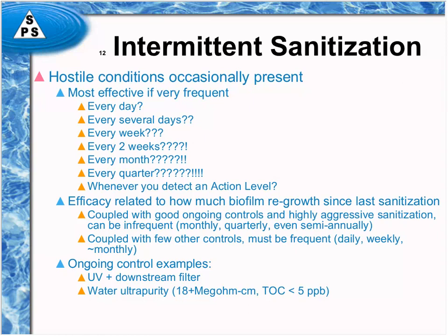When they have really, really high quality water like this, they almost never bother to sanitize water systems because the biofilm that's there grows so slowly that it doesn't cause any problems. The only problem with having purity like that is it costs a lot of money to make water that pure. So that's why it's not a common practice in the pharmaceutical industry, because people don't like to spend that kind of money to get that kind of purity all the time.